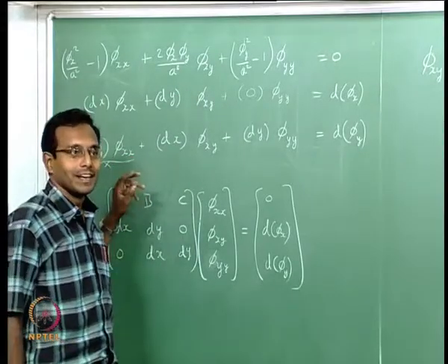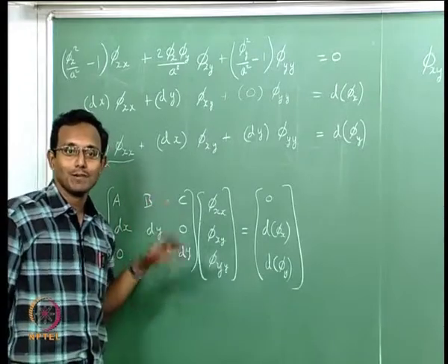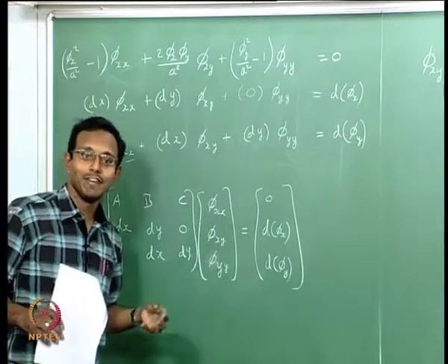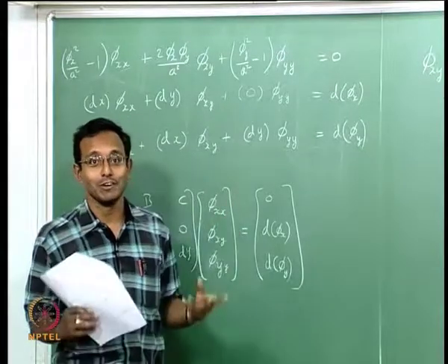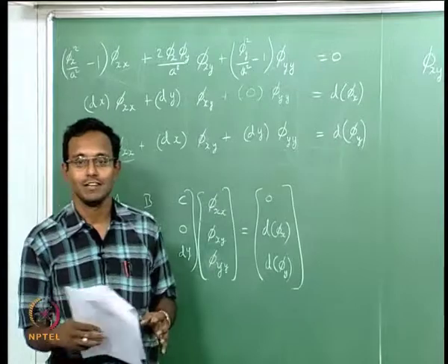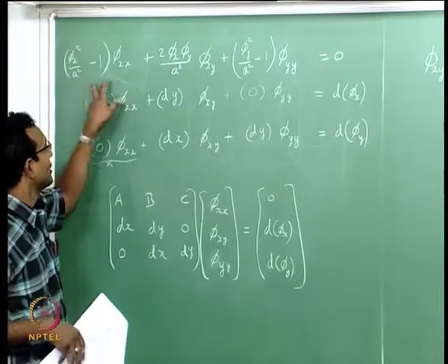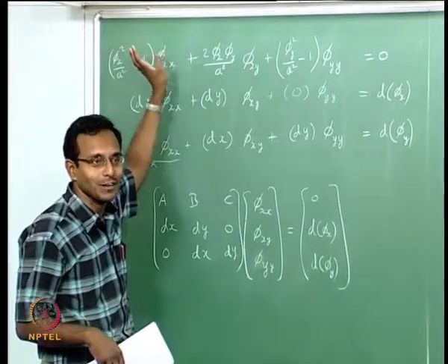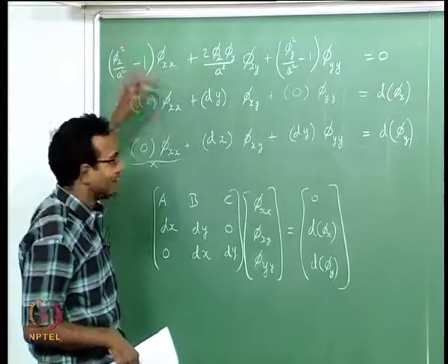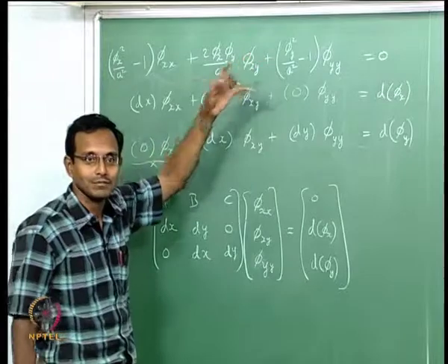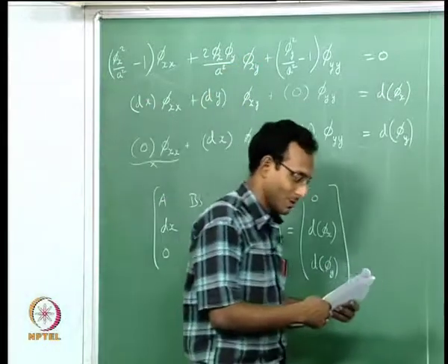So a tending to infinity means what? I am going to incompressible, that is, my waves are traveling extremely fast. If I make a change, immediately flow at infinity knows that I made a change. Okay. That is the idea. So that is also expressed mathematically in this form automatically. If my a is not infinity but anything lesser, I will get to this expression finally. That is the one more thing I wanted to talk about.